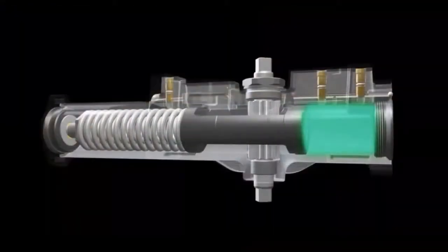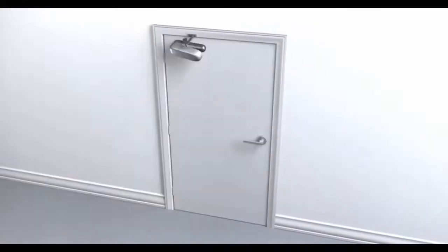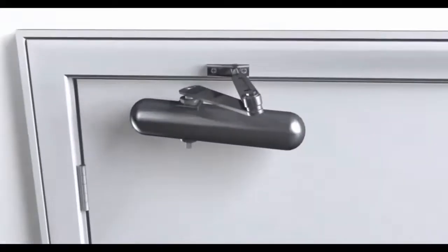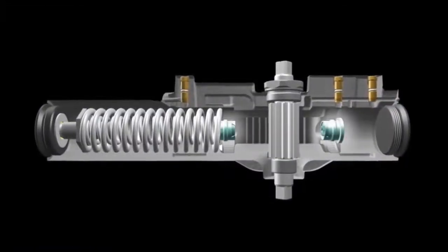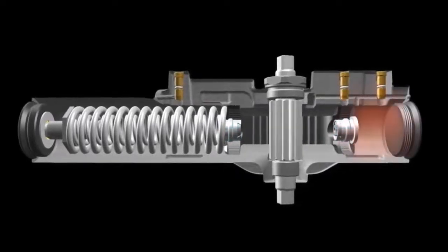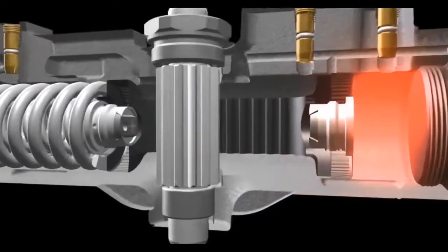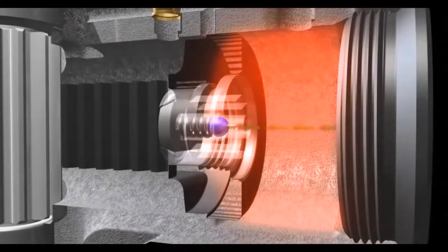In cases like these, extreme pressure builds up inside the closer body. With no way for the pressure to escape, that force can damage the closer, the door, the frame, and the mounting hardware. This is why our unique self-regulating pressure relief valves are so important. Under abusive conditions, the pressure relief valve on the end of the piston senses the extreme pressure and automatically meters the fluid to achieve more normal pressure levels.